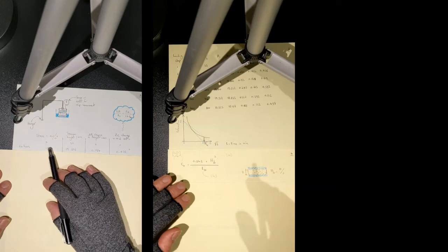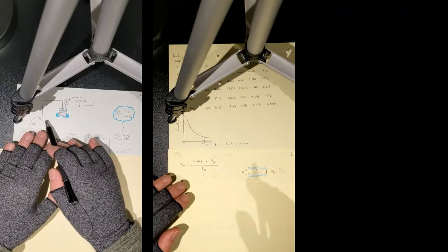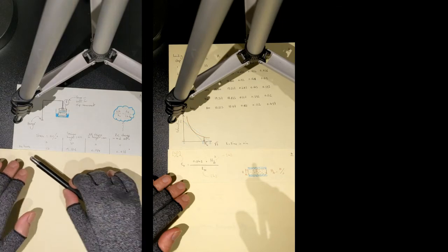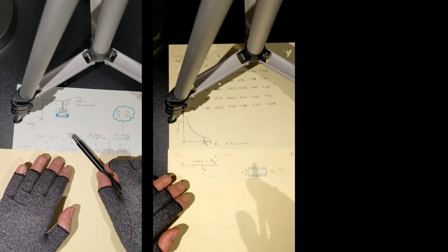The stress is increased from 0 kPa, the initial state, to 25 kPa. So you have got to apply enough dead weight on the hanger to generate this 25 kPa on your soil specimen.